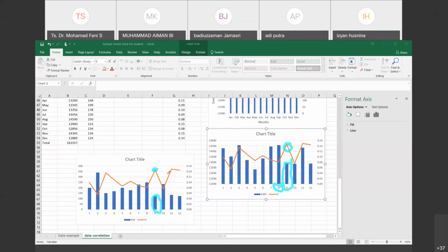Okay, that's one of the analyses that we can put in the report. So in order to improve the load factor, we must reduce the consumption of electricity and the maximum demand value. So when this balancing comes into practice, we can see the improvement of the load factor.